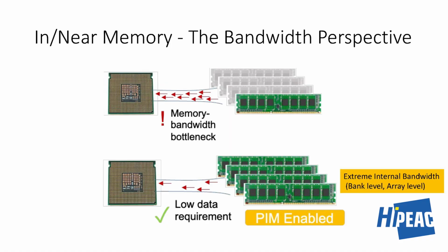The result, yeah, A plus B plus C, let's say. But here, if you do PIM, you don't have to read all of that data in. You just directly read it out from the banks and do the compute here. So you save all that data transfer. Yeah, that's right. Only the output, only the temporary results need to go, not the inputs. So that's what you save.